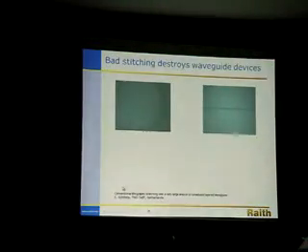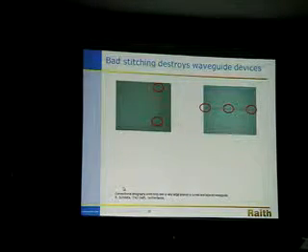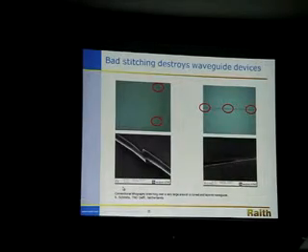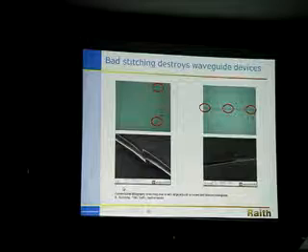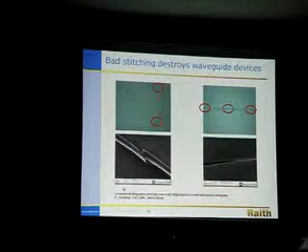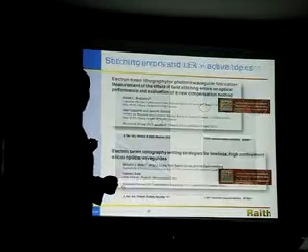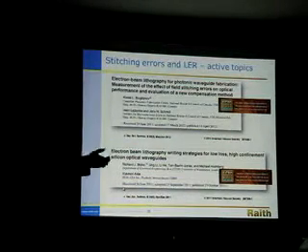Okay, so when you have stitching errors, I'm going to show you some really horrific examples of stitching errors now. These are some waveguide devices. These are extremely bad examples of stitching. There are even stitching errors that you cannot observe in the SEM that give photonics researchers problems. And that is why people are actively, even with $5 million instruments, getting together and trying to address the problems with stitching errors in their instruments and publishing papers, even in 2012, on this very problem.